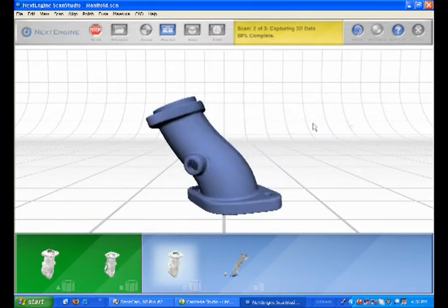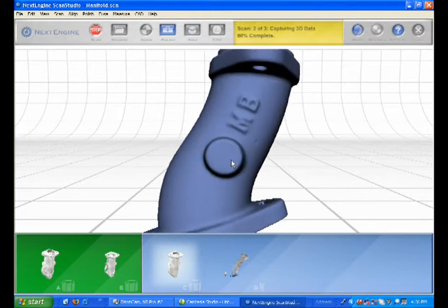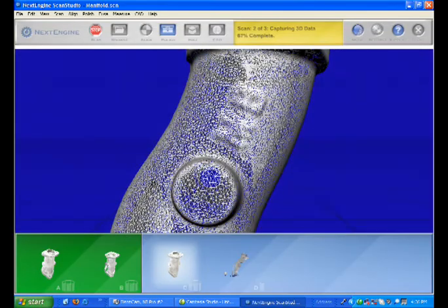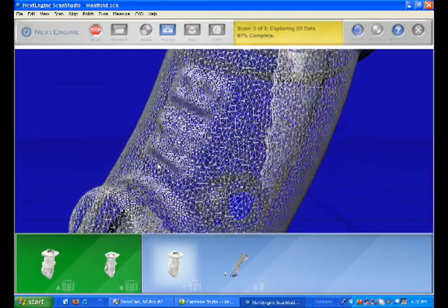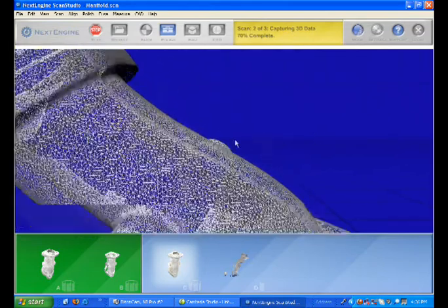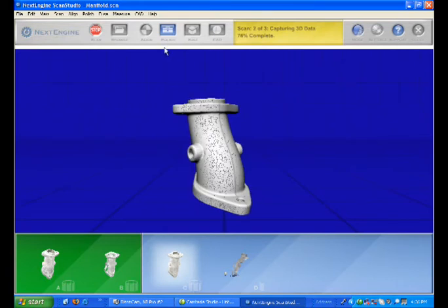So what fuse does, it does 3 different things. It basically blends everything together, it optimizes the mesh, and it hole fills in areas where you had maybe some slight occlusions that you didn't capture with the scanner. And Ronnie's going to point to the fuse button up top in our toolbar. This is one button that does all this.